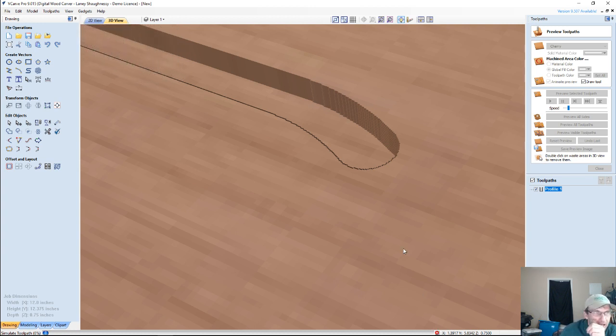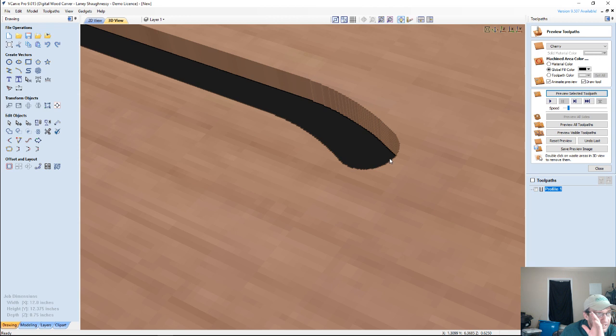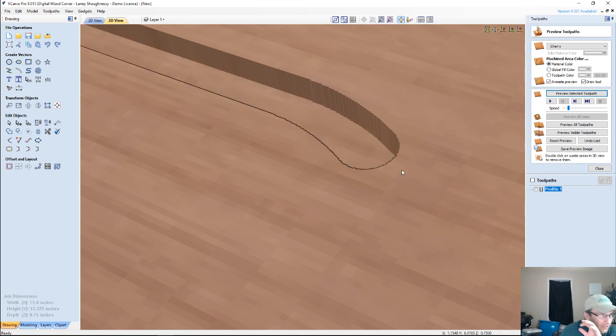It's just taking that full 1/8 inch depth of cut from the beginning of the lead in until where it starts cutting the profile of the toolpath. Well, if we ramp, it's going to do that nice subtle cut until it gets to the point where it starts making the shift into the profile toolpath.